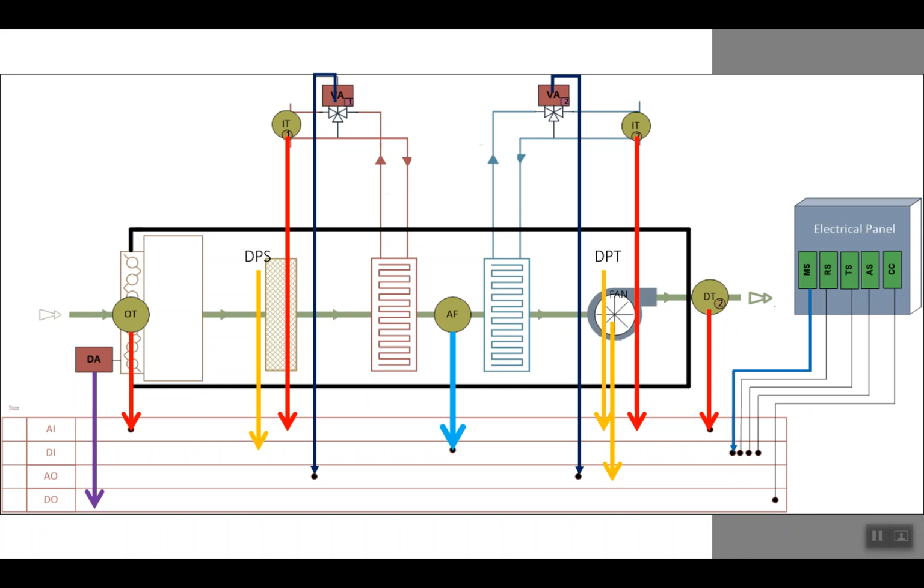In the electrical panel we can see the status if it is manually controlled, or we can see the status of the motor of the fan, if it's on or off. The next one provides us the trip or error in the motor, or the protection of the motor. So if it's activated, we can see the trip status.